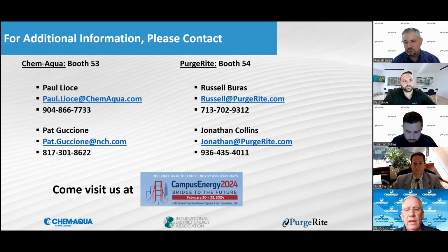The other thing is chlorine dioxide is present in the system as a gas. And as a gas, it moves through the system by diffusion rather than by circulation. And it's much more likely to reach any holdout pockets. So you're going to have to work with your water treatment provider. You're probably going to want to make arrangements to bring in a temporary or portable chlorine dioxide generator and try and add chlorine dioxide till you get to maybe about 5 ppm in every part of the system.